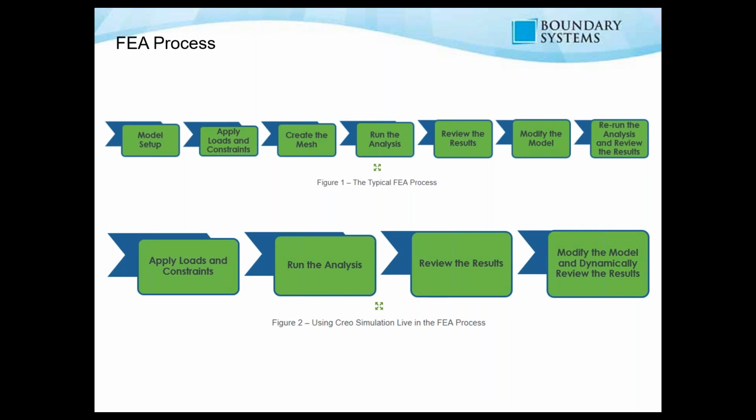Where with the new Simulation Live tool, you apply the loads and constraints. So note, there's no setup and things like that. You run the analysis while you are busy designing this. You review the results, so it's going to give you immediate feedback, and from there you can dynamically keep on reviewing as you make changes, and it's going to feed you that information. So there's no reruns and things like that. So really a great tool in the beginning of your design.